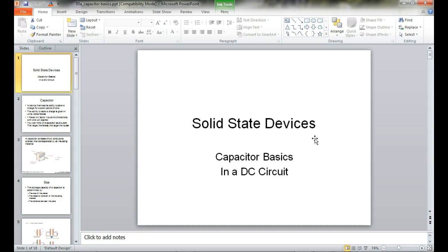Well, what happens is when you put a current load on the power supply, it has a tendency to go down, and when you take the current off, it has a tendency to go up. And it happens so fast, and it's away from your regulator, and your regulator can't compensate for that speed. So we have what we call decoupling capacitors, or basically filter capacitors, that get rid of all that switching noise that we would have in a digital circuit.